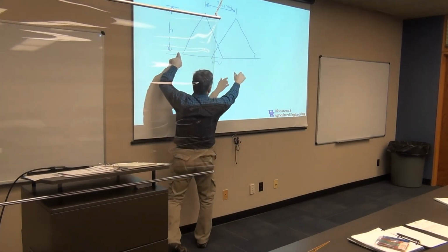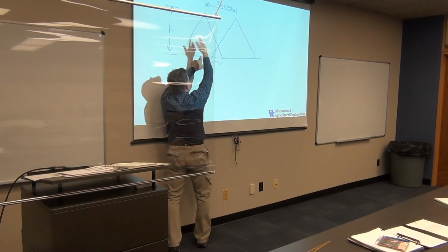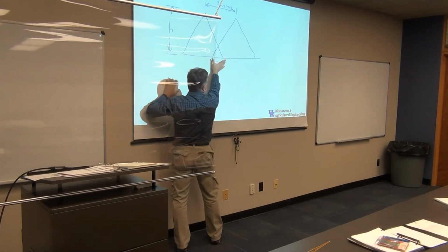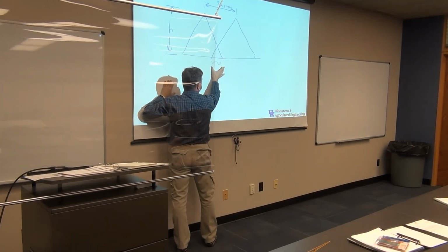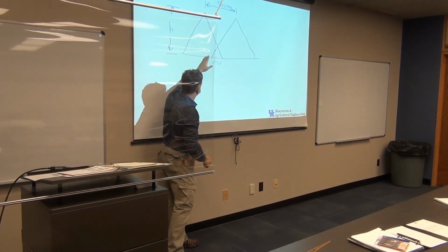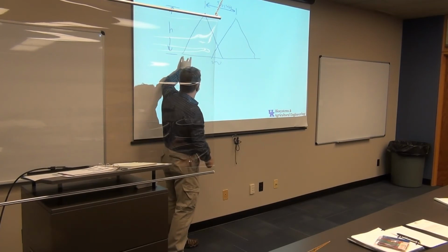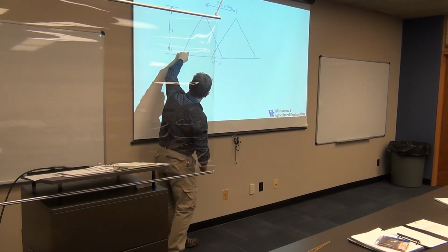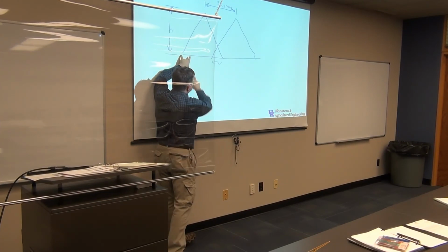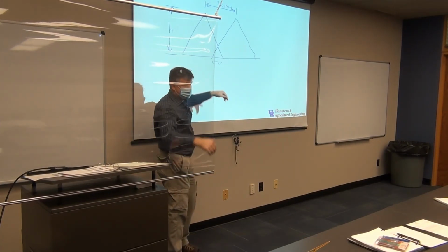Okay, so that would be 100% spacing. So I bring them in, so I have this one here, that one there, I've got the one in behind it, everything gets two. Here, like I've drawn it, only this area right in here is going to get material from two nozzles. This area over here is only getting material from one nozzle, until you get over here where this next pattern will come in the side, and then I'll have another area over here that's going to get material from two nozzles. Okay, so that's the overlap.